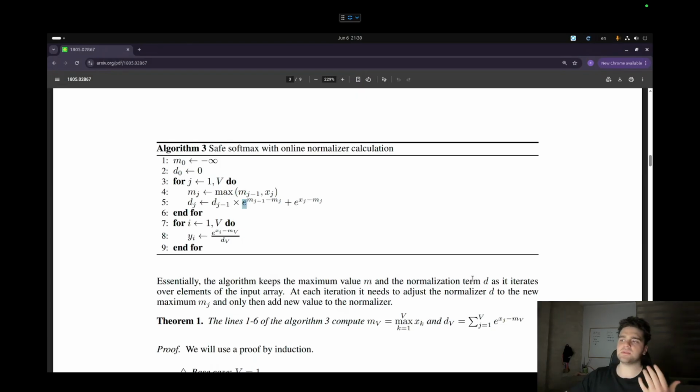What lookup tables basically are, is that you have a range of input values, and for this range of input values you have a range of exponential values. So you need to make sure that your inputs do not exceed that range, or you have to normalize that range. And after that, we also need to be always multiplying and accumulating an exponentiated value.